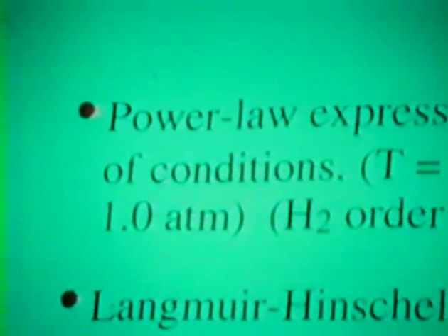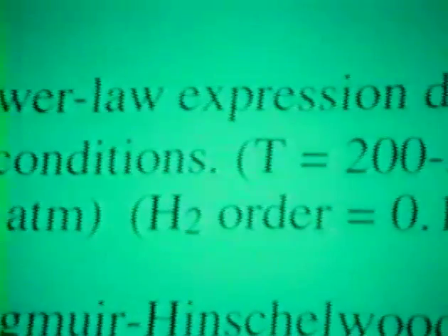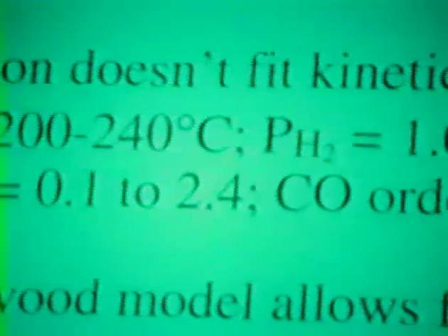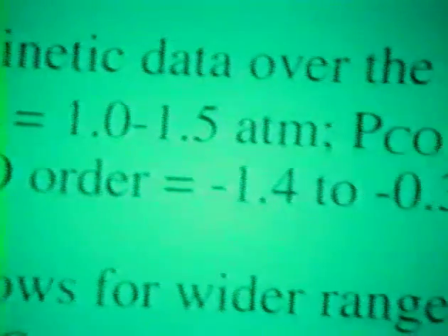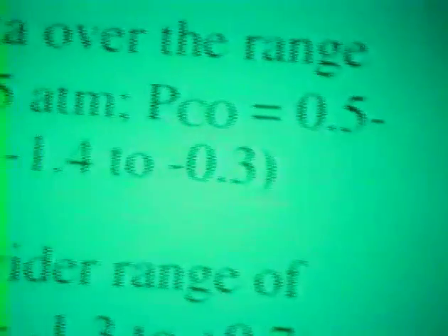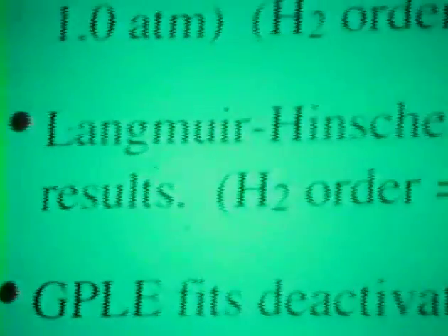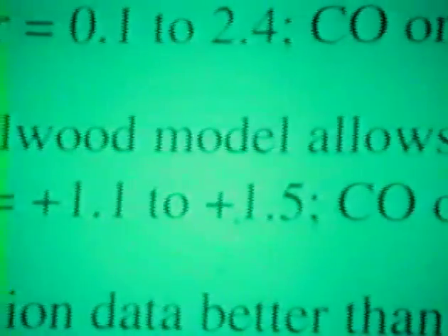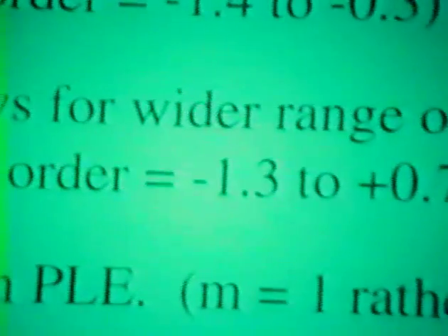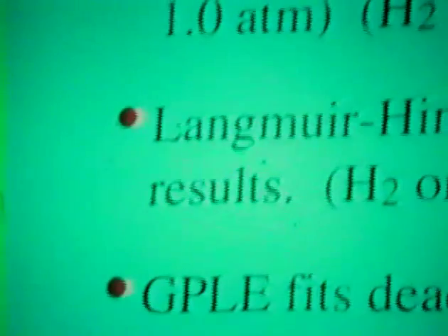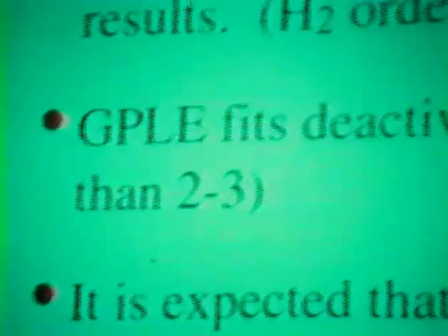Well, what have we found? We've seen that the power law expression does not fit the data very well over the range of conditions. And as might be expected, power law expressions generally fit over a quite narrow range. However, when we used a Langmuir-Hinshelwood model based on elementary steps, we were able to develop a model which did fit both the high pressure and the previous low pressure reaction study.